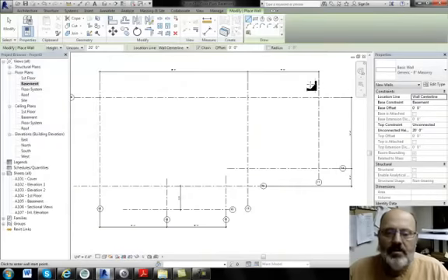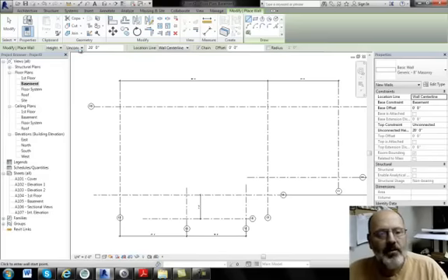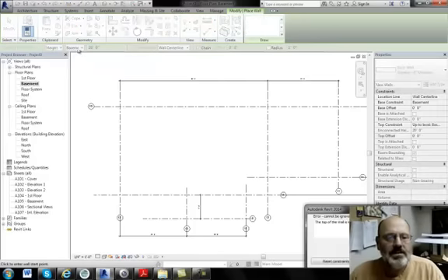The other thing I want to do, now this is picked and I've got it set up correctly, so it'll be set up that way for whatever I do in this particular drawing from here on out, is I want to draw these walls, but I do not want them unconstrained. See, it says they're unconstrained 20 feet tall. What I want to do is constrain them. I'm going to draw them basement. I'm going to constrain them to the basement level.